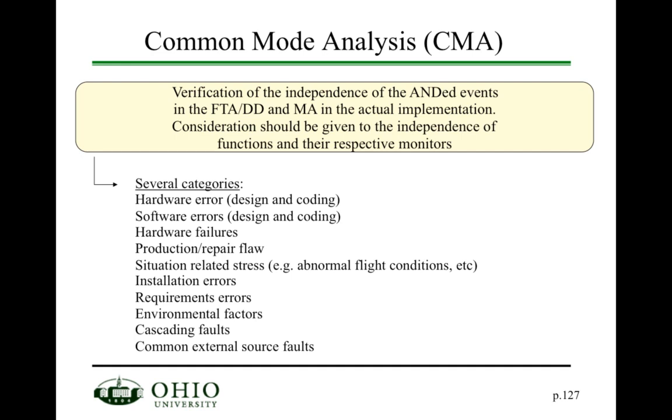In a common mode analysis, you're going to go to the fault tree analysis, the data dependency diagrams, the Markov analysis, and identify and verify if the independence is met in terms of hardware design, or for example, hardware errors. There could be errors, for example, in the design or coding that are common because of common design teams or common approaches used in the hardware and software design.